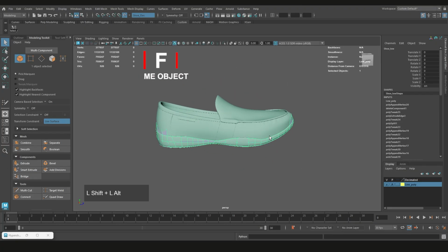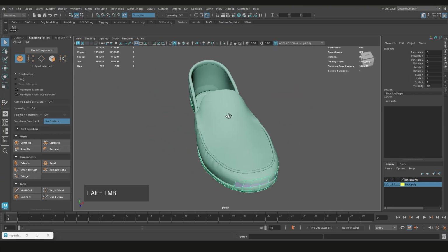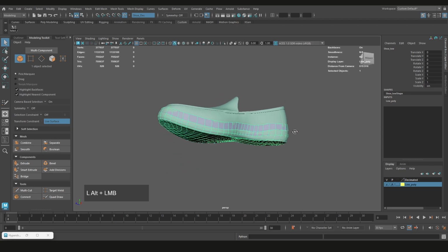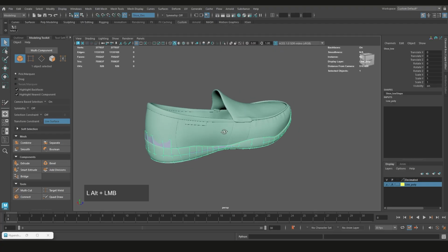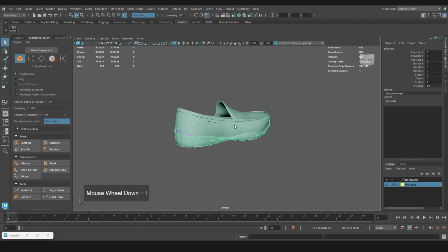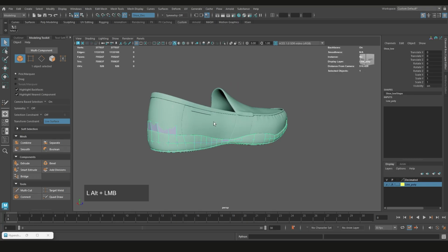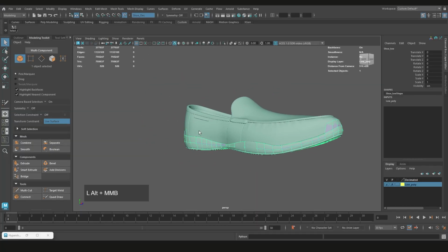And don't forget about your Alt-Shift-D to clear the history over here. All right, so yeah, Alt-Shift-D is just something you're going to have to get used to with Maya. No program really has that, so it's a Maya exclusive pretty much. But yeah, as you'll notice your program slowing down, you're like, why is it slowing down all of a sudden? And then you'll notice this building up, so it'll become second nature. So yeah, again, let's get back to the retopology, and then I'll fast forward through that, and then get back to you guys with anything that I need to. Okay.